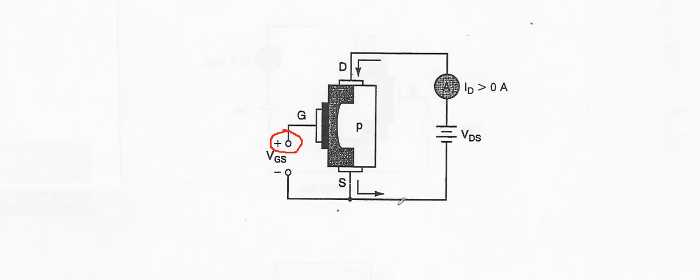For a P-channel E-MOSFET, you would apply negative voltage to the gate to turn the device on. And I think you can see it gets a little tricky maybe to hold it all in your head. The transconductance curves, doing a quick sketch of those is the best way to straighten it all out if it starts getting confusing or mixed up in your head.